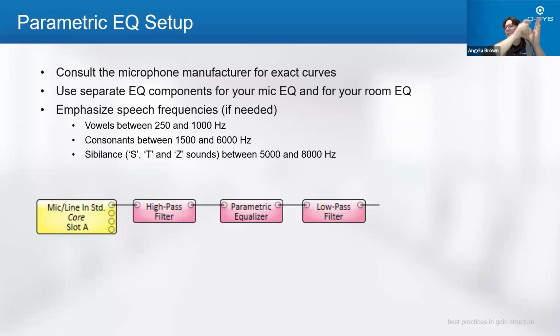Maybe on microphone 1, you have to take out 3.15K, and on microphone 3, you have to take out 7K. Then you even that out, even though they're different microphones with different elements in them, and you can make your AV system sound consistent. And that's really our goal.